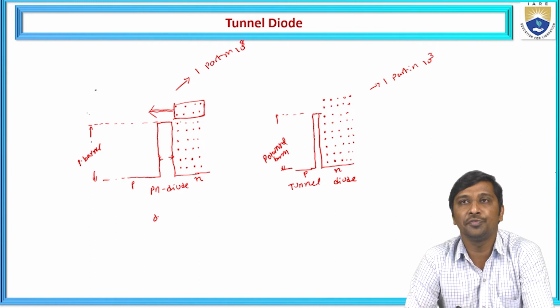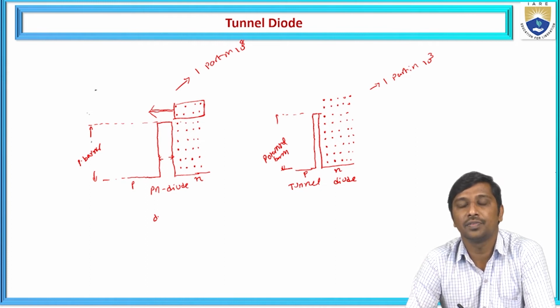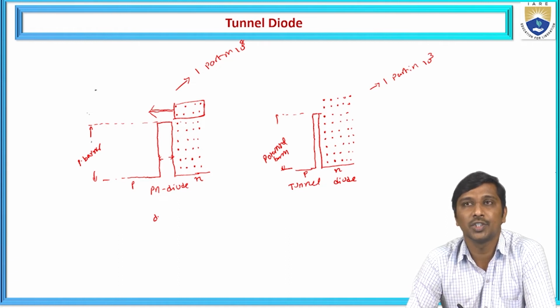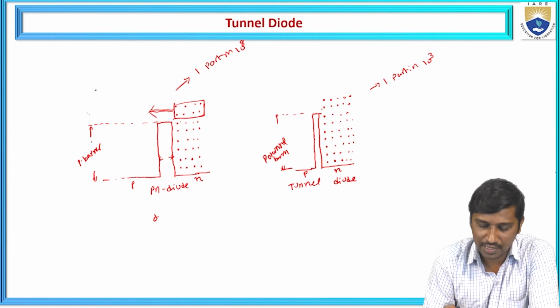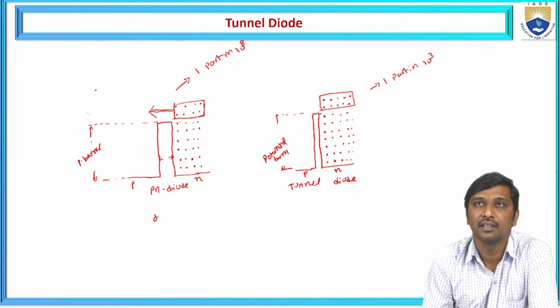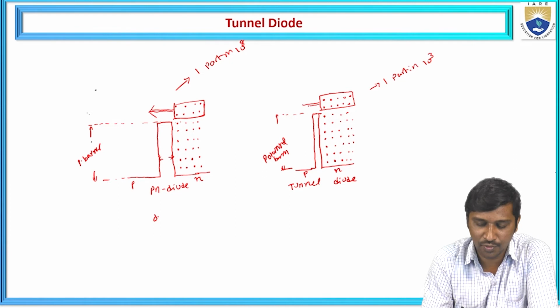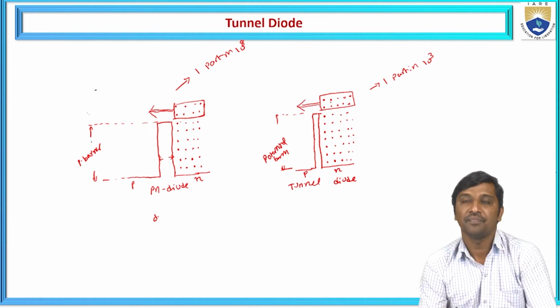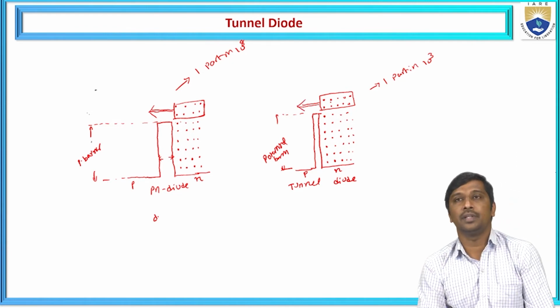If you want to diffuse the charge carrier, the potential energy of the charge carrier must be higher than the space charge region. Let us consider these are the charge carriers. Now we have the higher potential compared with the space charge region, hence they easily diffuse from the n side to the p side to allow the conduction.